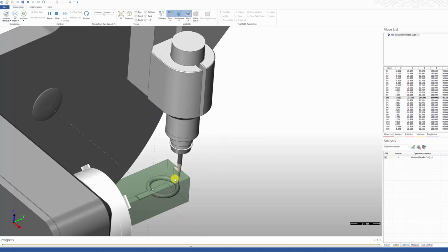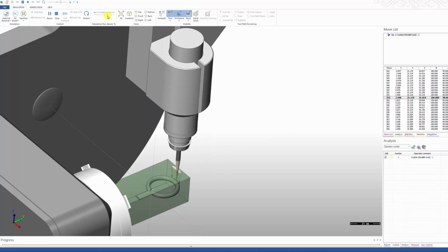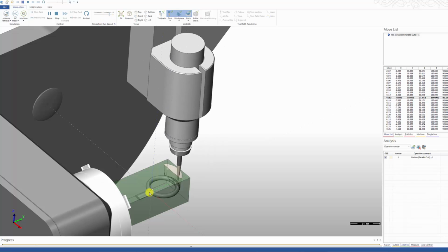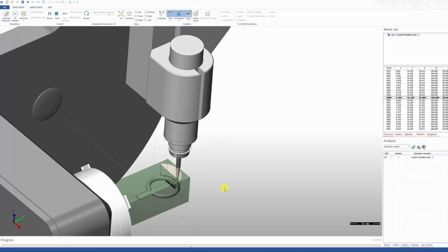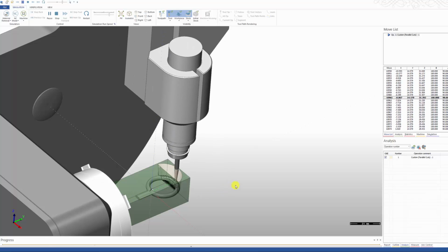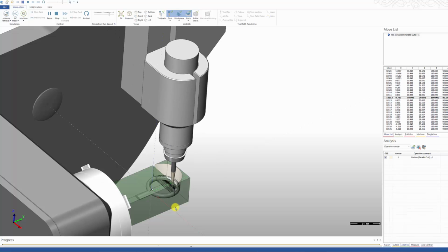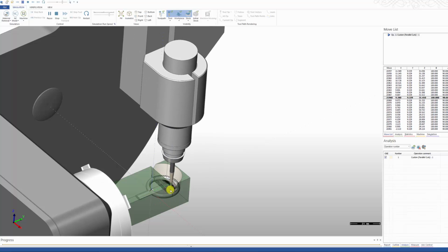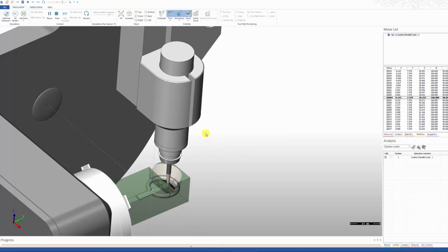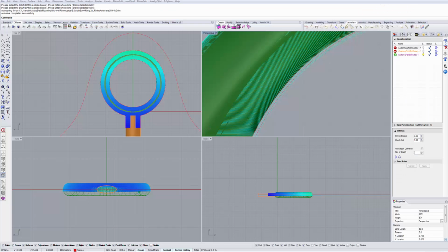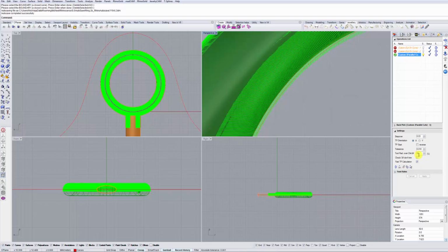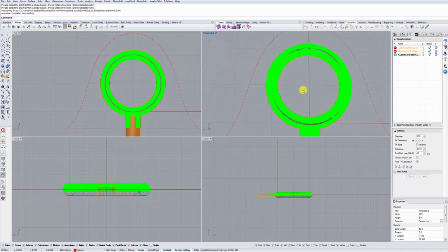And you see it begins correctly at the point furthest away from the stock holder, moving slowly towards our chuck. This is good. This is the correct orientation and the good way of cutting using the X direction. If it started here and moved that way, we would have to reverse the toolpath, and we could do that by checking this TP start as reverse once and clicking apply. In this case it works well, so we're happy with it and we will leave it.